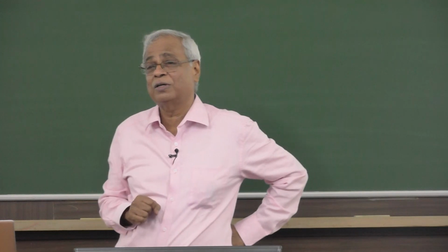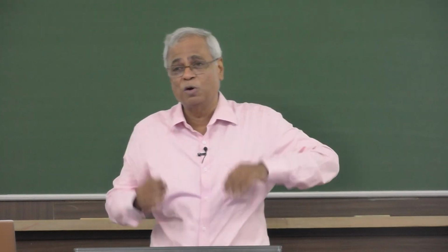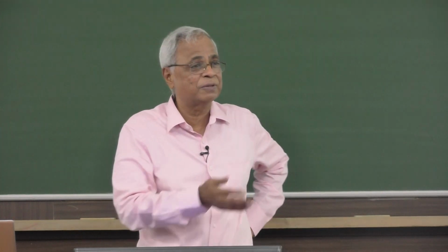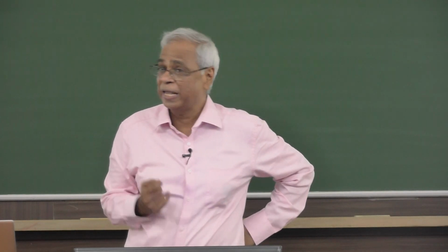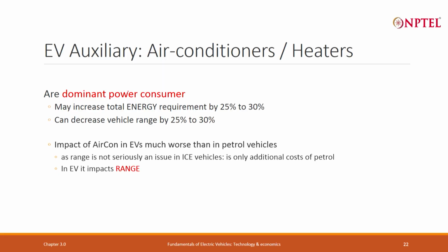Not so for an electric vehicle. The battery will anyway give you limited range, and then you take away 25% to 30% of the battery energy for using things like this. Your range significantly goes down. So, I want to point out that the impact of air conditioners and heaters on energy consumption is felt much more in EVs. It impacts range, and range is very valuable.